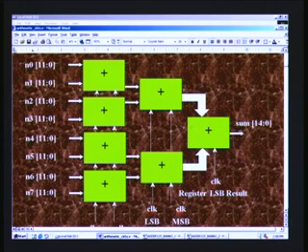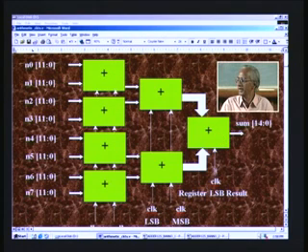again there is a clock input here, and at the arrival of the third clock what we would have done is we would have added the LSB of these 2 here, and with the arrival of the fourth clock we will be adding the MSB of these 2 inside and register here, and finally 2 outputs emerge from this here, and you can find once again an adder in the third stage here, and there is an internal register once again, and the final output is not registered, because that is the requirement for the DCTQ application,